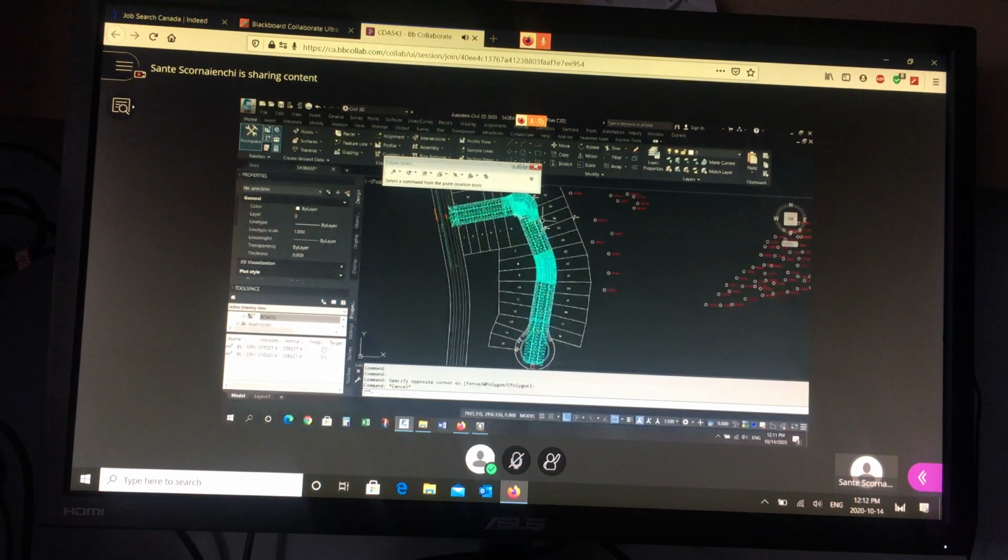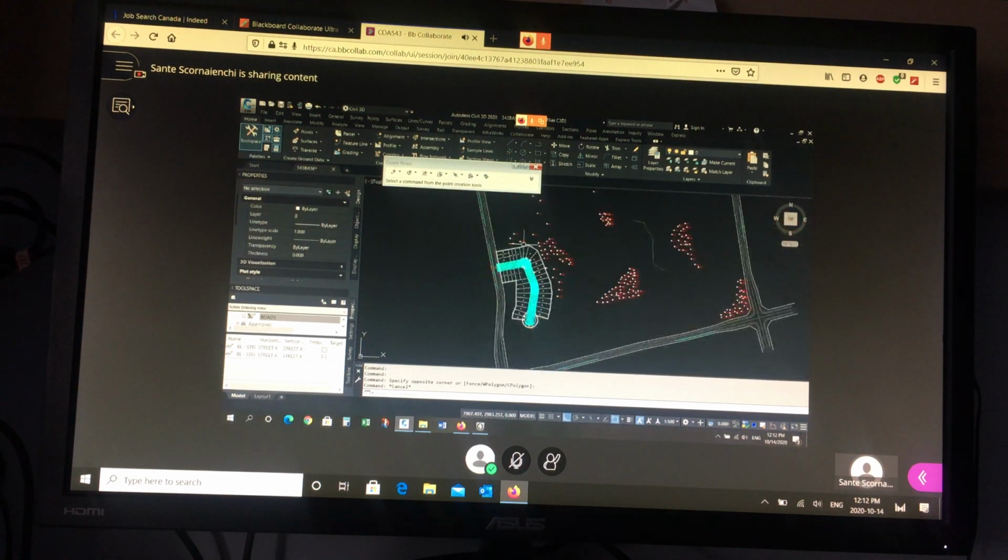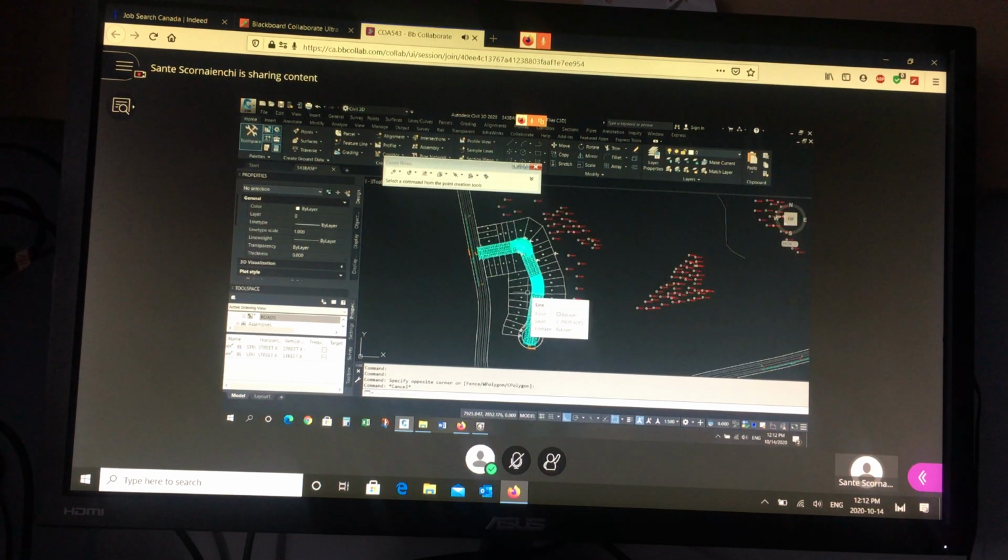Okay, and when you're done, you'll have points all along the front throughout the entire subdivision and all along the back through the entire subdivision. Front comes from this corridor surface, back comes from the existing ground surface. Okay, sounds like a lot of work, but it's not. The hard part is the corridor model. Once you have 2 surfaces, then it's just a matter of process.